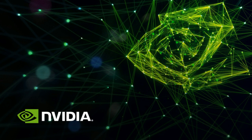Is there any GigE Vision camera support? Through GStreamer, I think there are a couple of different libraries that you can install that do GigE Vision in Linux, and different plugins for that. So if you look around, you can find different interfaces for GigE Vision cameras. Or some GigE Vision vendors actually have AArch64 builds available. Because typically with GigE Vision, the camera vendors themselves have an SDK. Point Grey comes to mind.